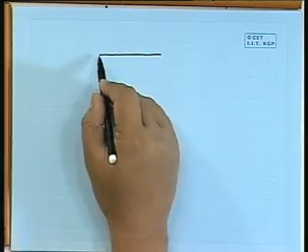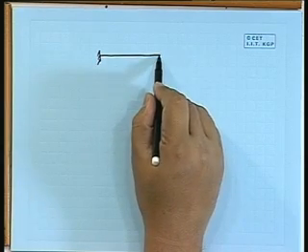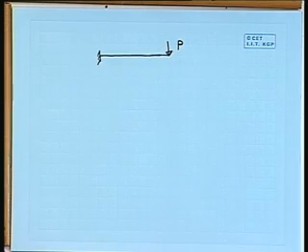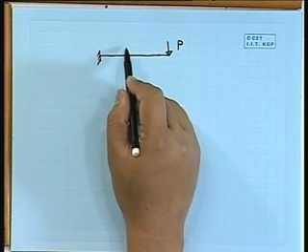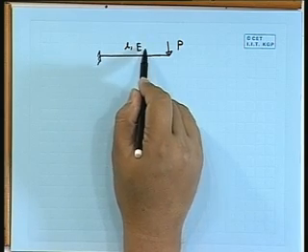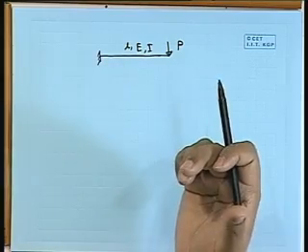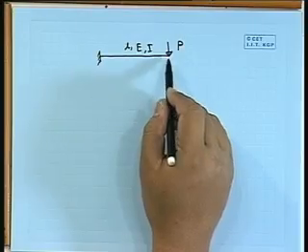I think if we take some example, it will be much clearer. Okay. Say you start with a problem which we have already solved by another method, so we know the result. Say it is a cantilever beam subjected to load P, right. It has some length L, some E, some I. So, length is L, E is the material property, I is the second moment of area. Now, due to that load, say we are interested in the deflection under the load.